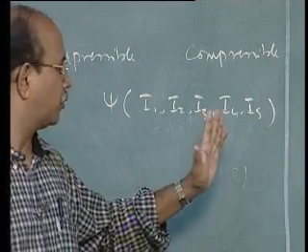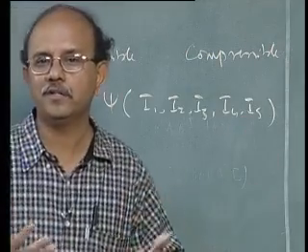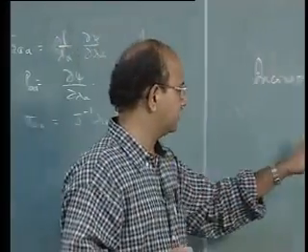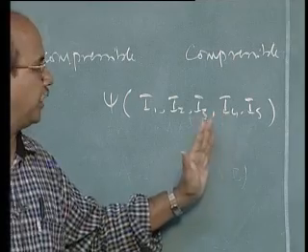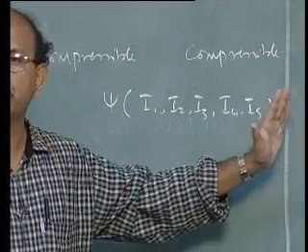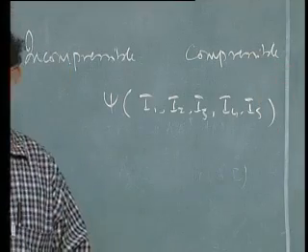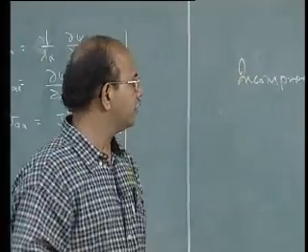These become important. So in which case, what is it that we do? We take a very similar expression, but the only thing is that we now have more than 3 invariants. Some of the purists still question what I4, I5 and so on mean. Are we correct? But people use it. I think it is mathematically quite sound. So people do use this, putting down a number of other invariants when anisotropy is encountered. It's a fairly new topic. Not much work has been done till very recently.